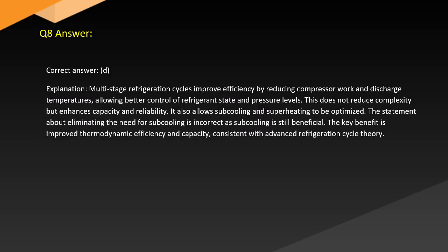Answer. Correct answer: D. Explanation: Multi-stage refrigeration cycles improve efficiency by reducing compressor work and discharge temperatures, allowing better control of refrigerant state and pressure levels. This does not reduce complexity but enhances capacity and reliability.